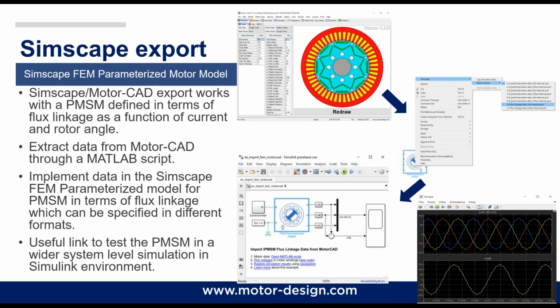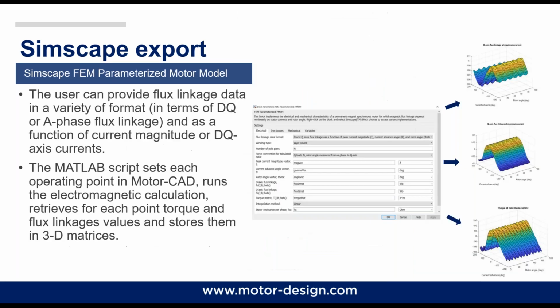Here we have an example of how to implement the model in a wider system level simulation. Here we have an open circuit test in order to show the nonlinear back EMF characteristics. So as I already mentioned, the user can provide flux linkage data in a variety of formats, which can be tabulated DQ flux linkages or A-phase flux linkage data. They can be tabulated using Cartesian or polar current coordinates.